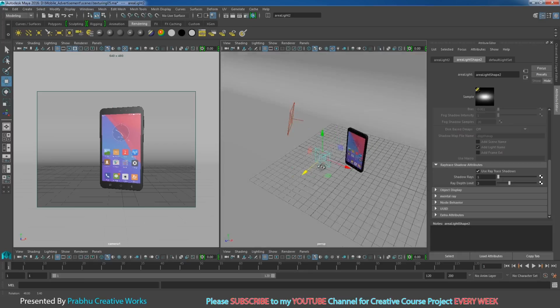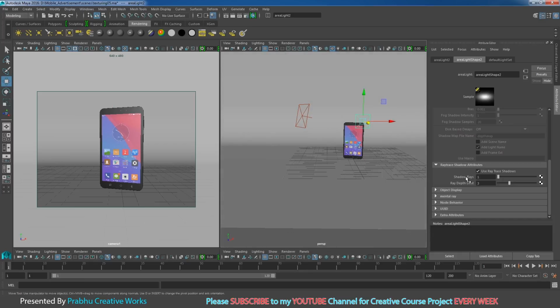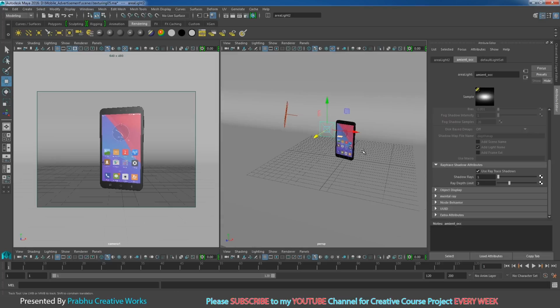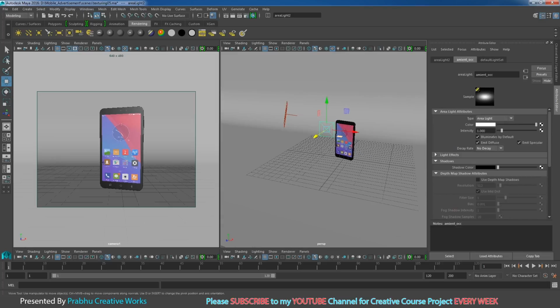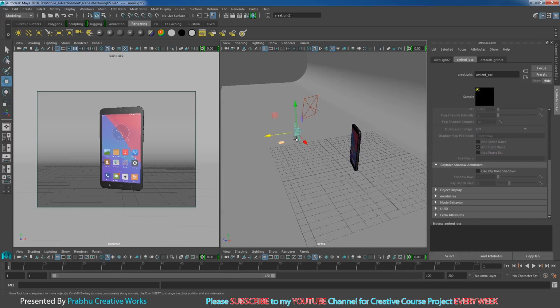You want to place it in front of your mobile. Here you want to rename this light as ambient occlusion. I don't want any intensity here, so I will give intensity 0. I turn off the ray trace shadow for this light.